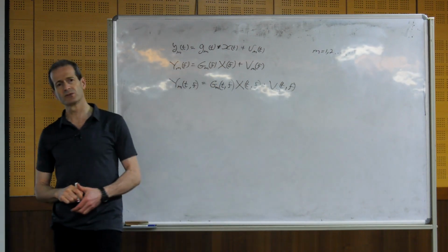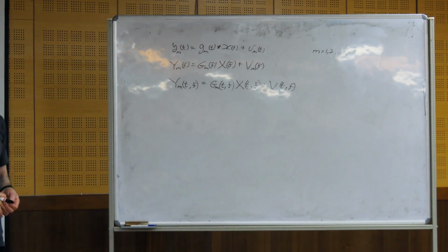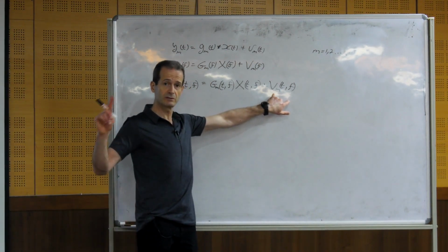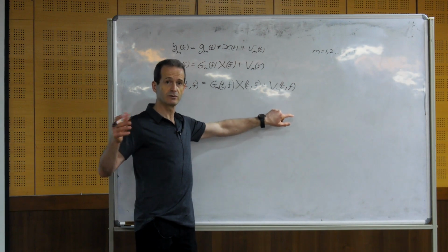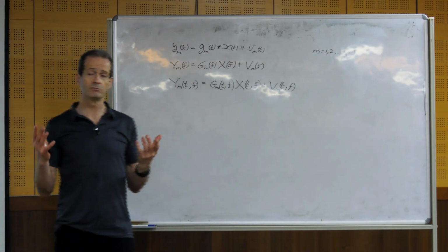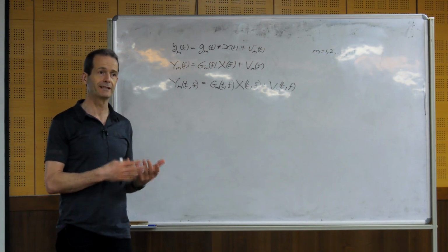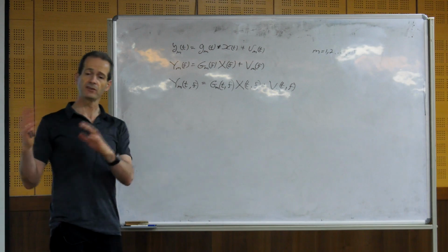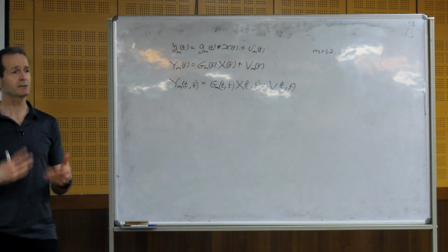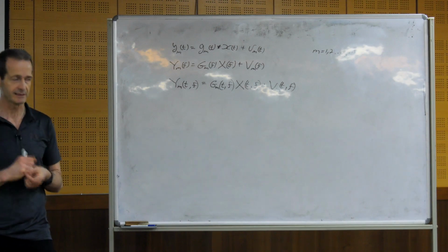And of course, you need also models for the noise. Sometimes it's useful to split, just like we talked about yesterday or the day before yesterday. We split the noise into at least two components. One component which is correlated with the noise at the reference signal, and the other component is the remaining noise components. And it's also possible to do additional things, but I try to simplify things, the basics.